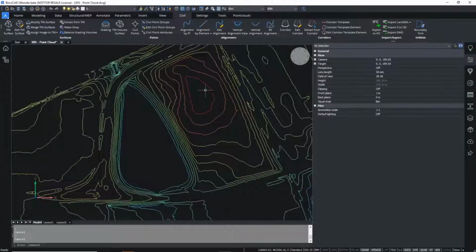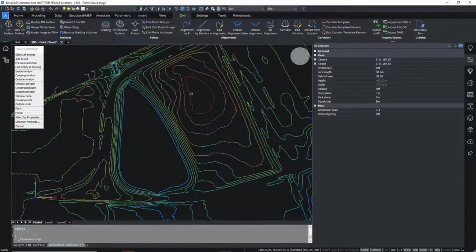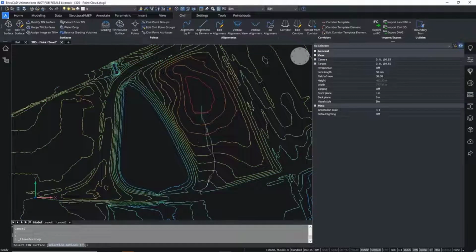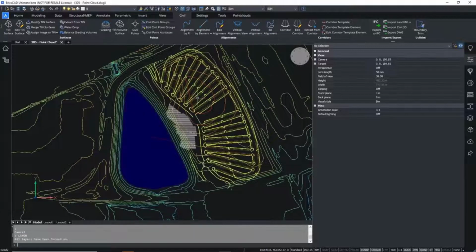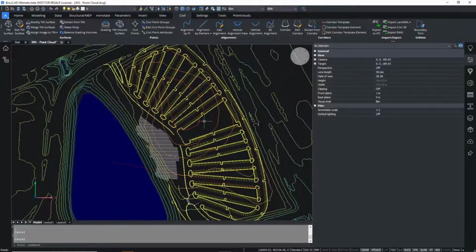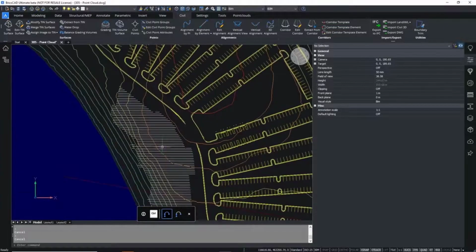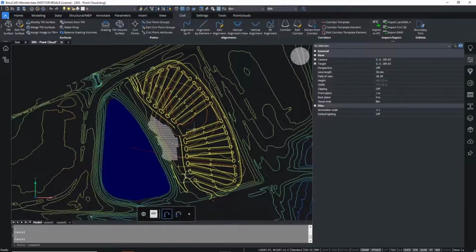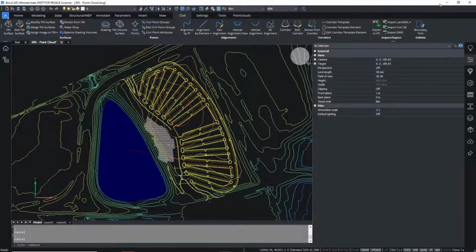And we can then go and do something like create the water drop. If we select this surface object, as we move the mouse around, we can clearly see which way the topology is flowing. So what we're going to do is create our car park site in this area where the mouse is now and have the building in front of this lake. If I turn my layers on, you can see that we've already drawn up this system here where we've got the general car park layout and the building footprint shown. So what we'll now do is switch into Civil Site Design and start working on that.